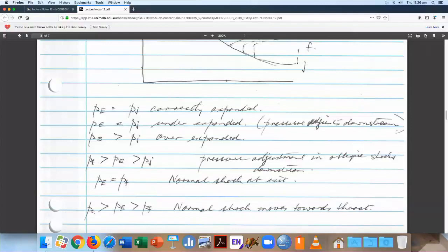And the assumption is that people don't want to have normal shocks in this nozzle, even though they are bound to when they launch the vehicle, because it can lead to instability. It can drive the thrust off the axis, which is what you'd like to have in a rocket, and if it's off the axis, then you have to try and bring it back by gimbaling the rocket nozzle. And you can run out of, as I mentioned on the Titan IV, that's exactly what happened. They ran out of gimbal control.